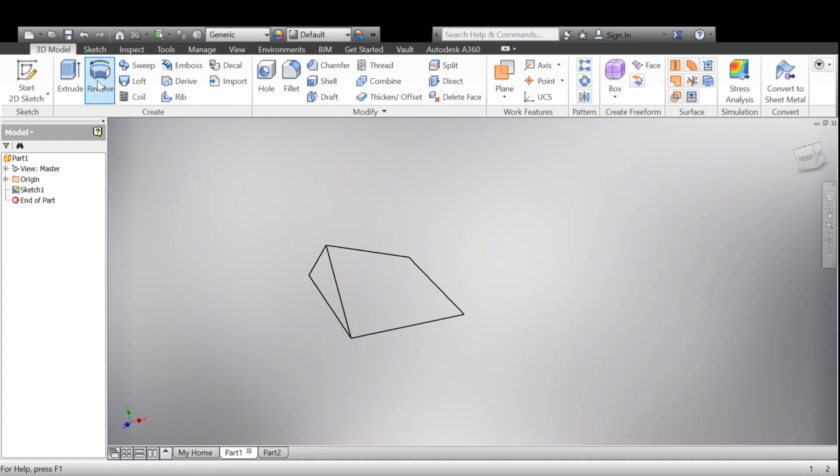So I'm going to choose revolve as my option. When I click on revolve, it's going to pop up with a window that says, again, profile, right? This word profile is really important. A closed region I'm calling a profile. And then axis is going to be important. Why do you think axis is going to be here, but it wasn't here last time? This option was not here for extrusion, but it is here suddenly for the revolve feature.